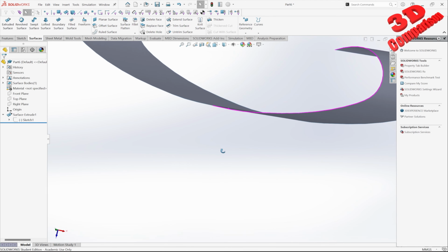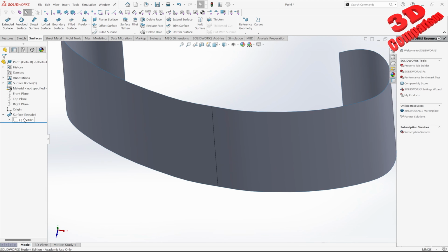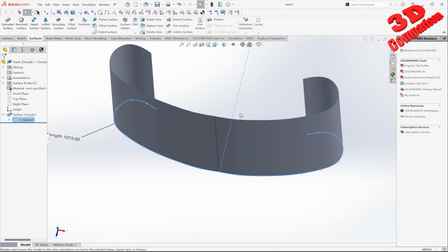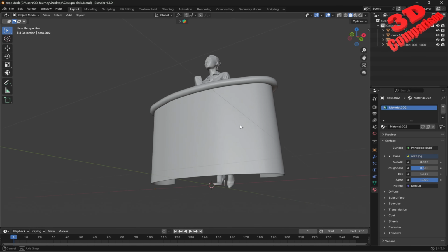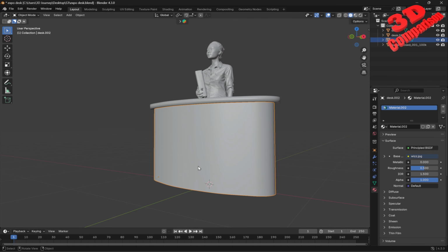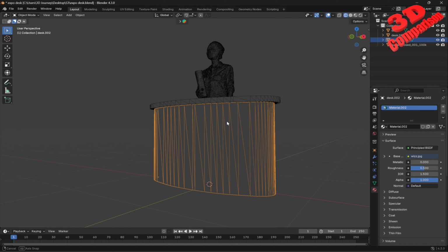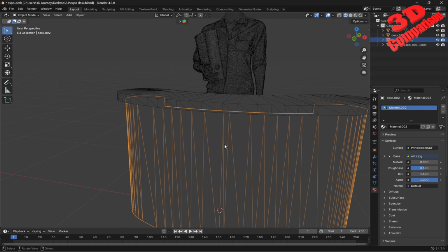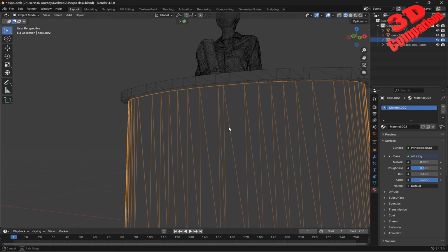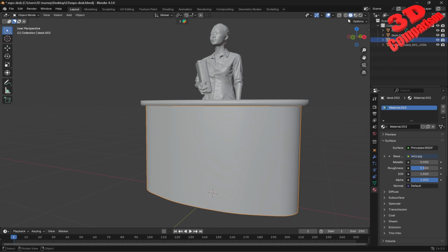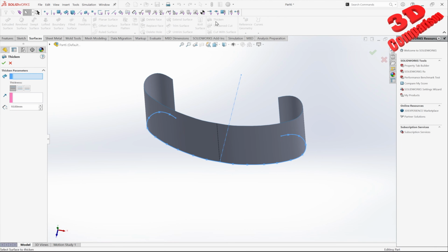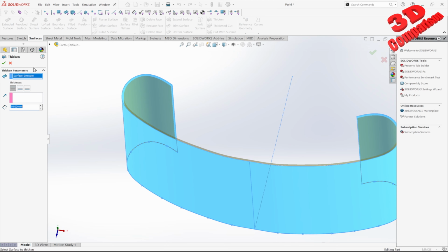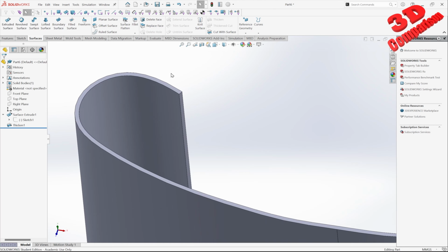Over here within Solid we have that visible since this has been modeled like this. But when we're going to take this within Blender, for example, we're going to see that that middle edge will no longer be visible. And if I will check the geometry, we see that this will be the following geometry of that model saved as an STL file. So I can add a thickness. In this case, for this desk, I will go inwards, and we have that designed.